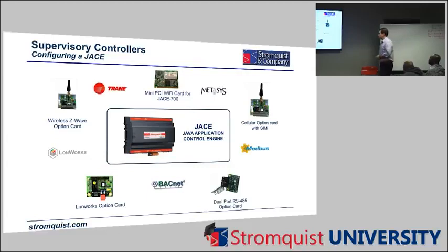Now, it doesn't stop right there. You know how when you have to get the driver as well. So that RS-485 card, like I said, talks to several different communication protocols. And when I install it, it doesn't do anything until I install the driver, which says, hey, this card is going to be used for BACnet. If I wanted to use this card for Metasys, the Johnson Controls N2, then I'd put that driver in.